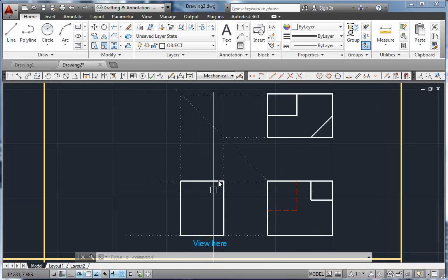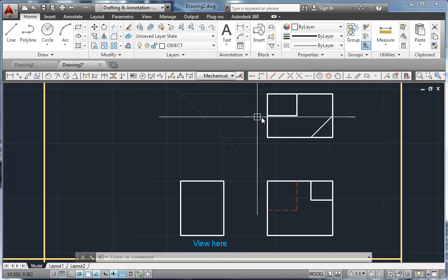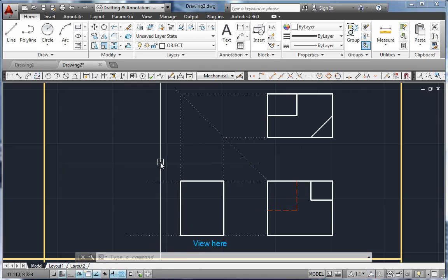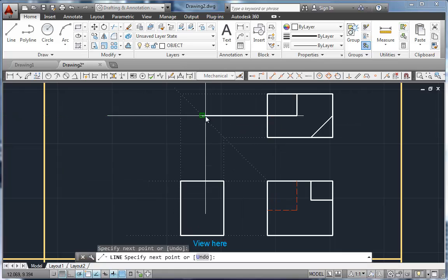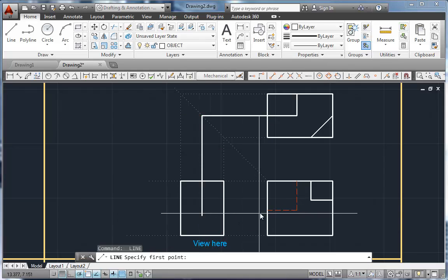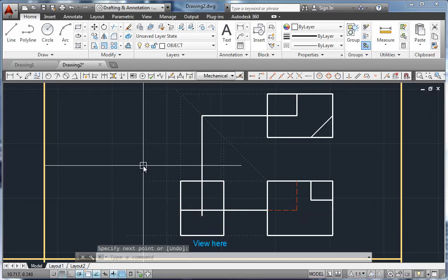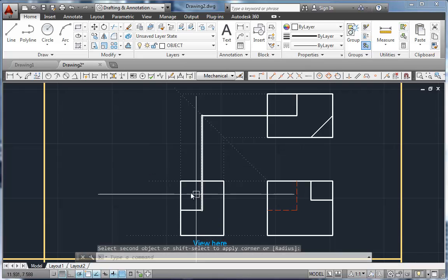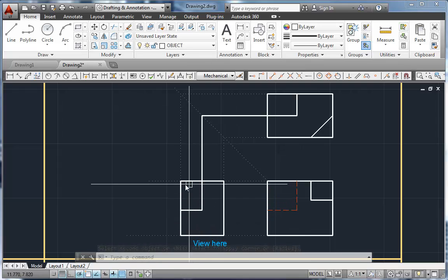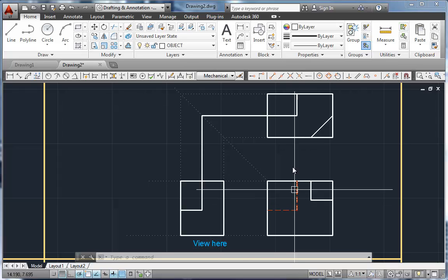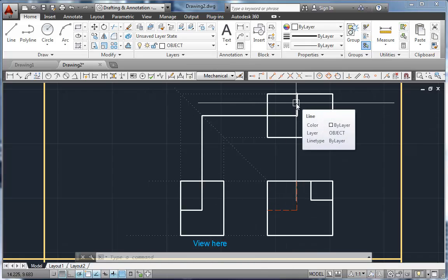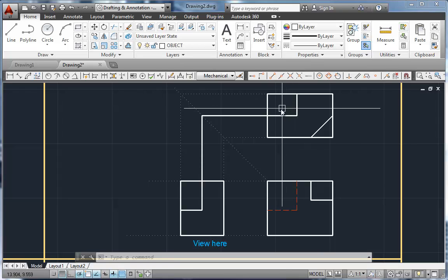In my side view over here, I'd be looking in this direction, from out here looking in this direction. I would see that notch. It would be visible to me. So I should expect to see that notch as visible lines in this view. So I'm going to take a line over from that surface and just bring it down, and then I'll bring a line across and we'll fillet that corner, and that gives me that surface is right there, and this is this back surface.